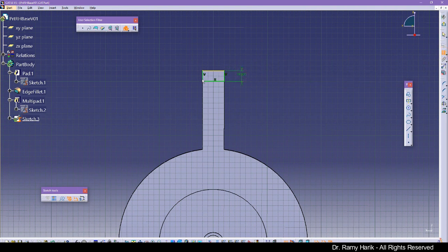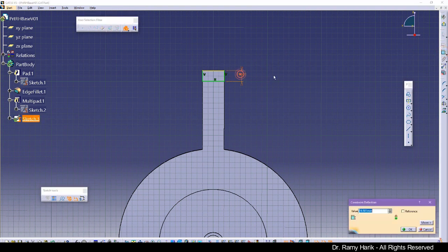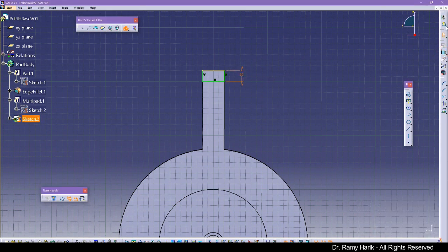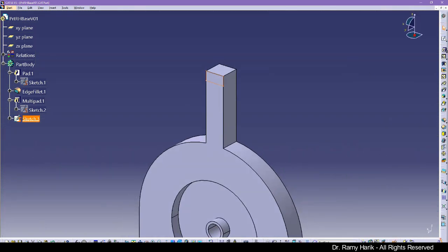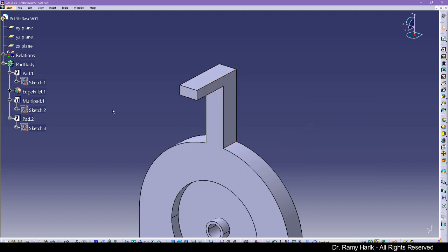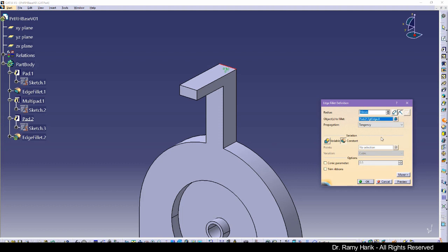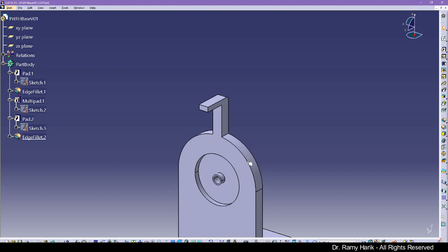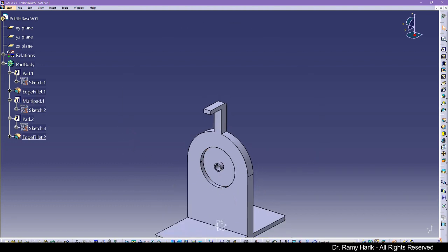This is a dimension, this is projected. So actually it's already all good. We just need to adjust this to 20. And we are going to extrude this from here. And we had a remaining 80. Preview. That is perfect. So we have in here a fillet, we can start filleting if we want, a fillet of 10. Preview. Okay. Did I forget any fillets anywhere else? Yeah, here at the bottom.